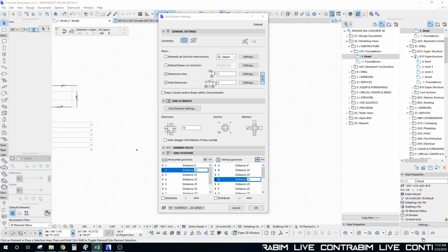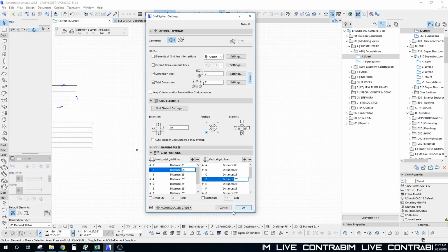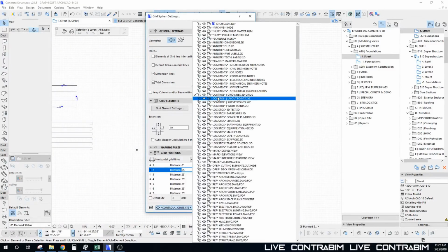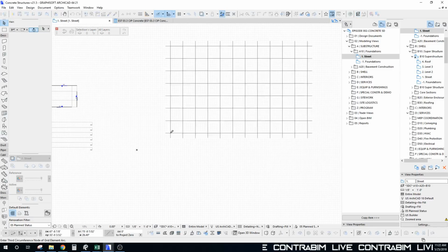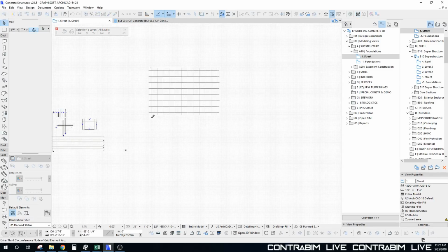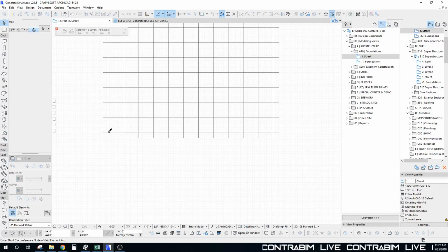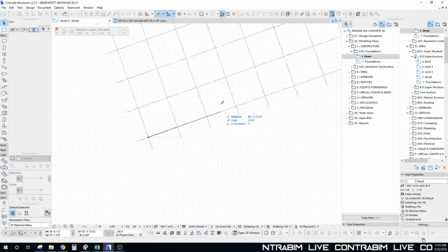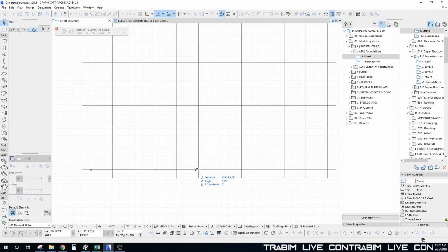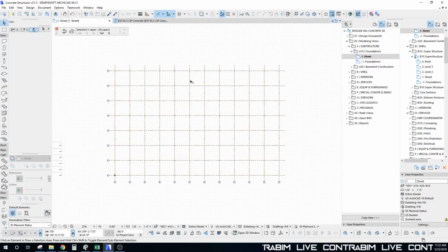And so, okay, John, go ahead and hit that OK and place it in there. Oh, layers. Under control, I have a few different types, either layout points or grid lines or working points. So, okay, there's our grid. Let's go ahead and place it right on the 0 right there. And in this case, I'm not giving it any type of rotation. So just click and add that to the project.